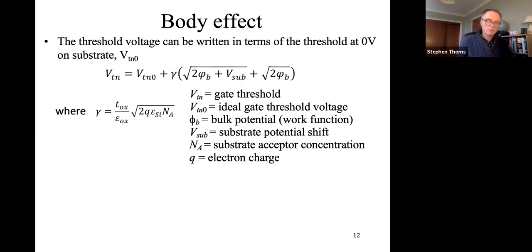So if the semiconductor potential goes up, then we need a correspondingly higher potential on the gate to actually enable conduction. And yes, you can just pinch it off by raising the substrate potential.